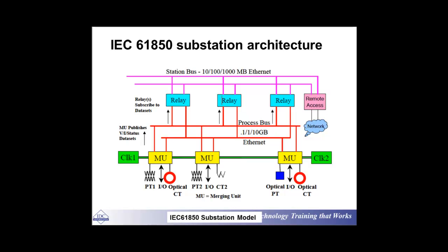That communication, if it is 61850, as I said, most of the time is Ethernet, which is a kind of LAN, or WAN. So basically it is LAN or WAN based. This is what we call the network. The sending of the information is very quick and reliable, and it is based on LAN or WAN, in particular Ethernet and TCP/IP. So these are the things that are used.